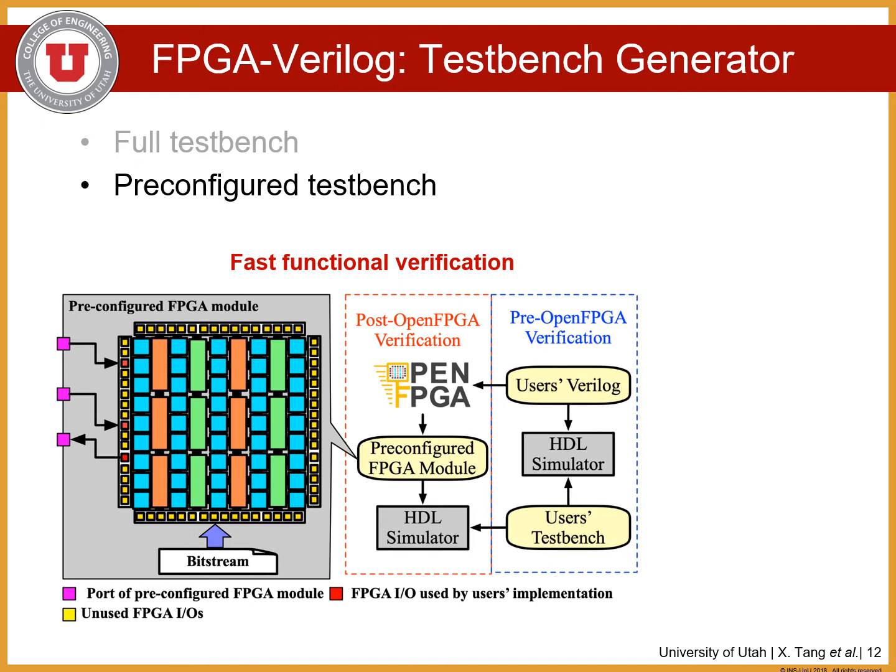You can see we propose a pre-configured FPGA module where we encapsulate the FPGA fabric with the configured bitstream into the same port mapping as the user's implementation in Verilog format, so that people can use this pre-configured FPGA Verilog in the post-OpenFPGA verification without creating additional testbenches.